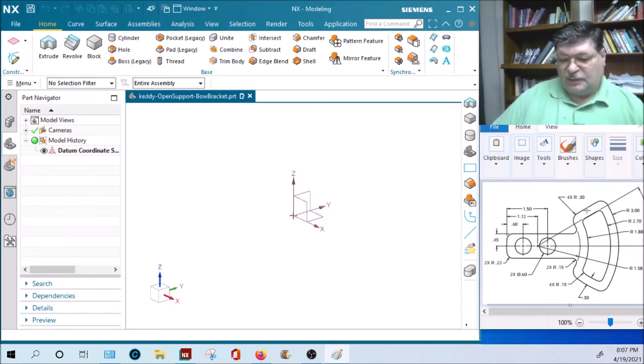There's another thing you have to notice, and that is this line right here on the brace, on the open support. If you were to extrapolate that line downward, notice it goes through this point. What is that point? That point is the center of all these 4 arcs. The arcs are a radius of 3, 2.7, 1.88, and 1.58. They all have a common center.